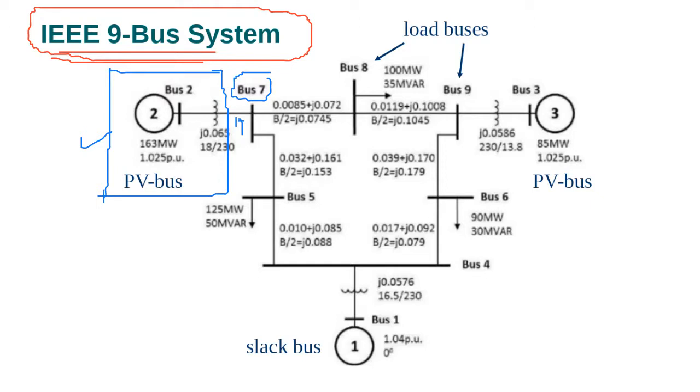Then you step up, therefore the current will be low because the voltage is high. Same power: VI equals the power. Of course, power equals voltage times I times cosine theta. So the cable will be small, as you can see in the picture before, very light, very small, at 132 kV. That's enough because it's 132 kV. So the current is low.